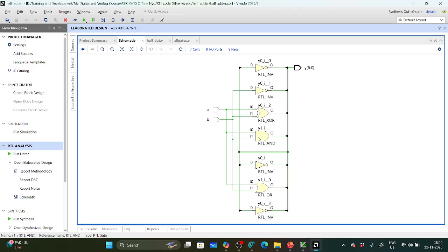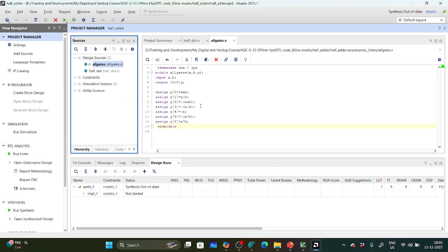That means based on our program, the circuit is converting into hardware. Basically in digital, suppose if you design any half adder or full adder, how did you do it? First you draw the truth table, and next you draw the K-map, and from the K-map you get the logic expression. From the logic expression you draw the logic diagram. This is the process of designing combinational circuits, no?